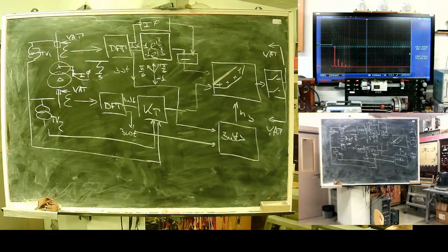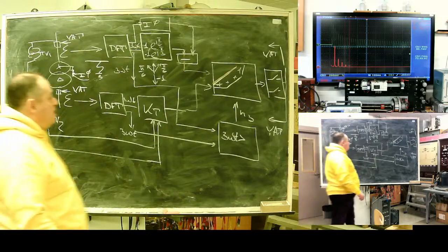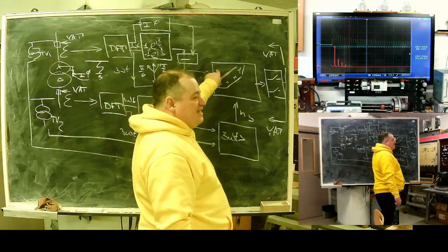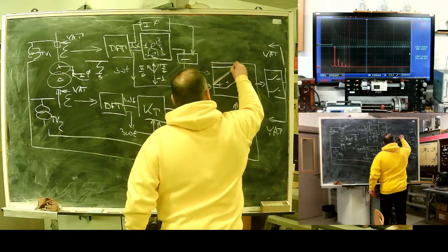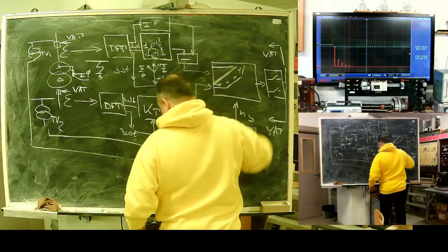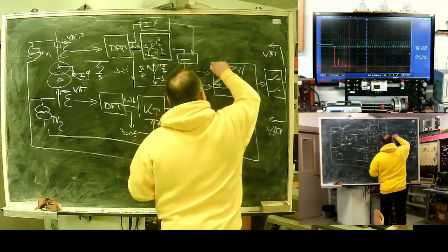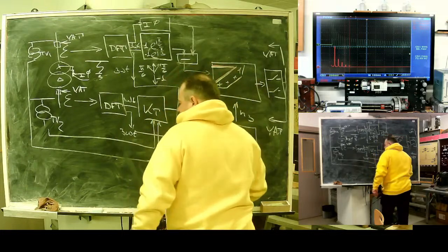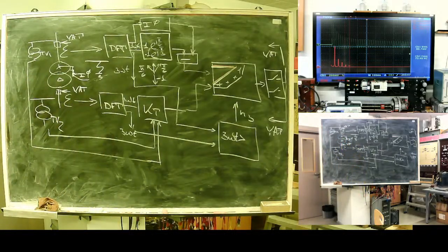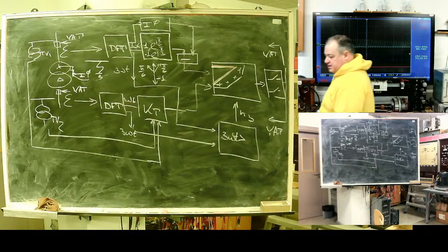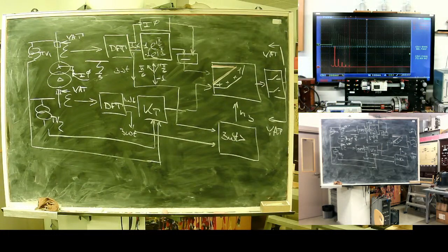In case of switch on to fault or severe damage in the transformer, this characteristic can have an instant operation, shown in red. It's an instant operation characteristic where a bypass is activated for rapid disconnection.